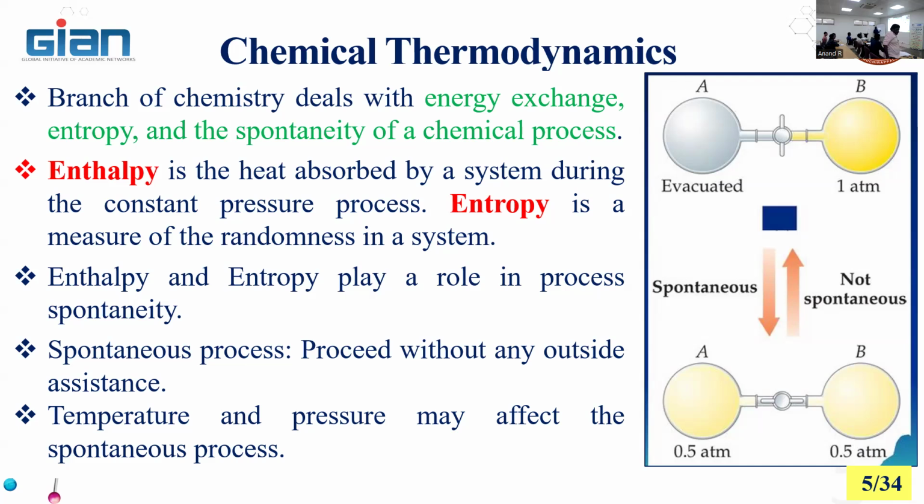Assume that the process is happening at constant pressure. In order to find W, we integrate P dV. If the pressure remains constant, that means P times (V2 minus V1), so P V2 minus P V1. That means mR times (T2 minus T1). So that is W. Except for internal energy, other forms of energy are assumed to be zero. You can take delta E equal to delta U, which is m Cv delta T between 1 and 2, so m Cv (T2 minus T1).